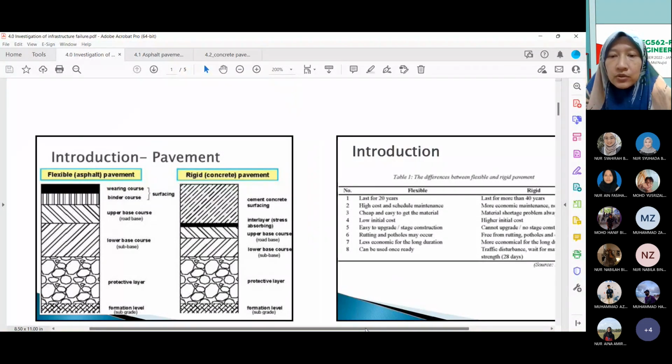So the purpose of road construction: when you design and construct the road layers, there are a few factors involved. For example, considering the route design, and then considering the dynamic load coming from the vehicles. Is it passenger car unit loading, or do we have lorry trucks? These are the factors included when you are designing the pavement or road construction.